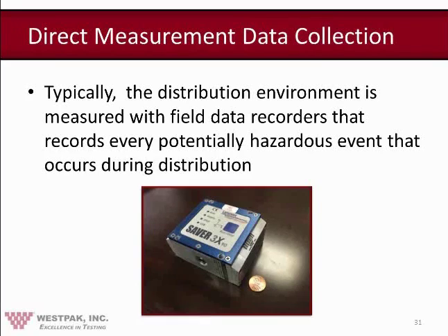Today they're incredible. They have the capability of recording both impacts, impact mode as they call it, and a timed mode. During the impact mode, this is kind of interesting, shock levels above a predetermined amount will be recorded. So in other words, the shock has already passed, and it goes back, remembers 20% of its memory earlier, and says, oh, better remember that one. That's pretty cool. In a timed mode, the recorder will turn on for a preset period of time over a preset time interval. So you might want to have it turn on for 10 seconds every 5 minutes, for example, and it measures typically vibration during that period.